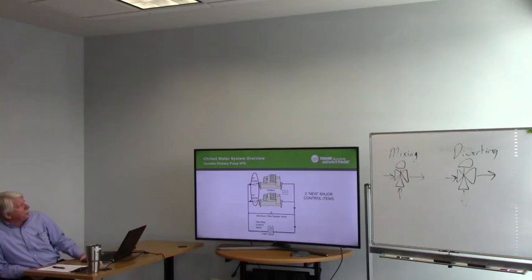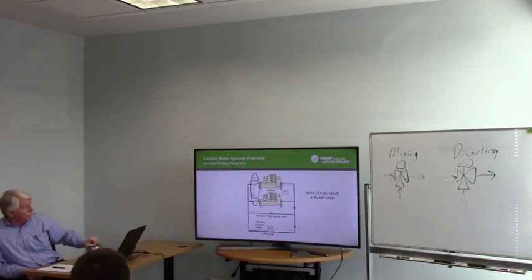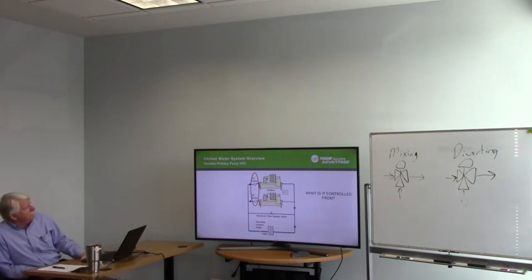Okay, the other new major control item is the VFD on the pumps. Why do we have a pump VFD? To vary flow. Okay, and why do we want to vary the flow? Based on what the system's asking for. Okay, we've got two-way valves out there on the coils. The amount of cooling that's needed out there in the system is going to change depending on the positions of the valves. And that's traditionally controlled from a DP.